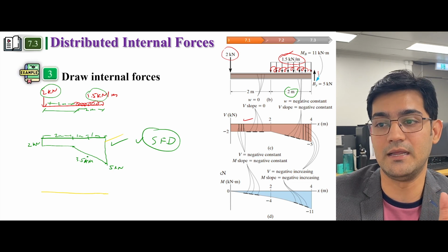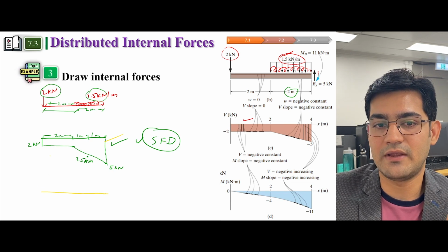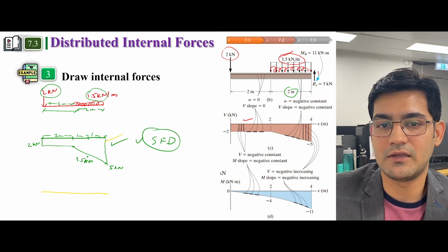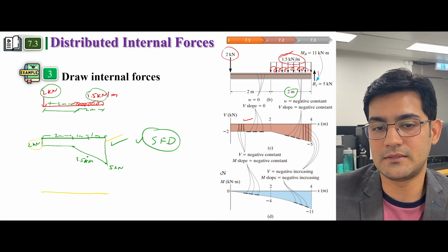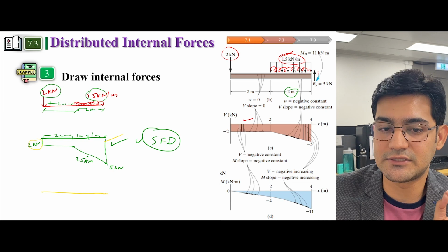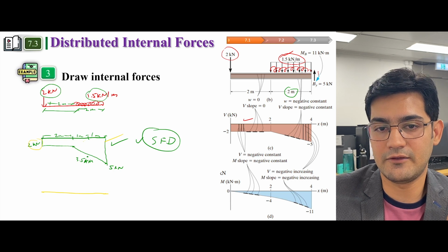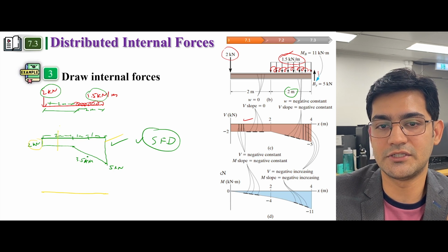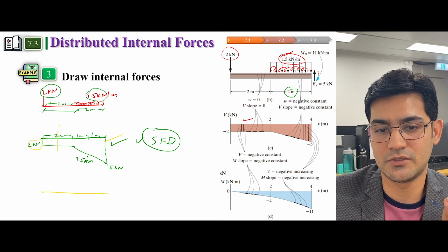to calculate the bending moment. So how we have to calculate the integral is, you have shear force which is 2, but at that point, at the start, you have distance 0. So 2 multiplied by 0, you would be getting a 0. And if we go to distance 2 meters, so 2 kilonewton multiplied by 2, you will get 4.